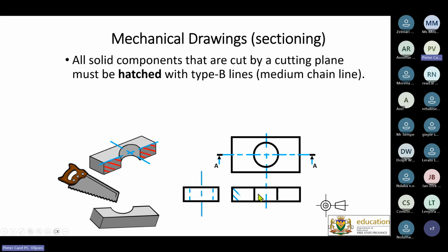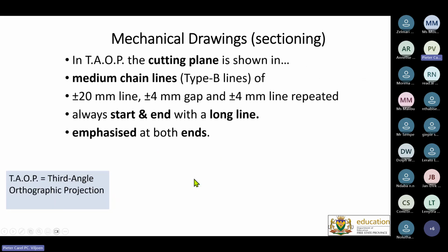And that's what you will see, a solid line, hatch lines, and hatch lines on the other side. Why not hatch lines in this part of the view? Because it's never been sawed up or cut by me. It's been cut by coming out of the factory itself.